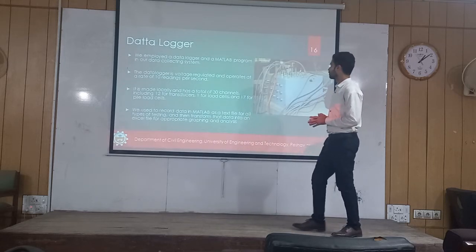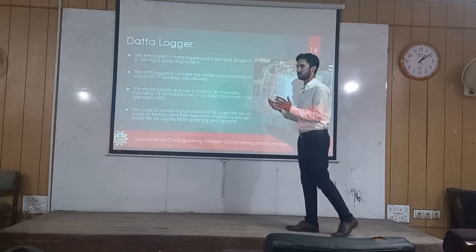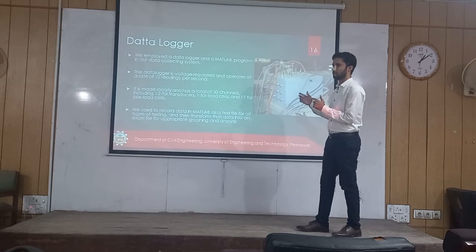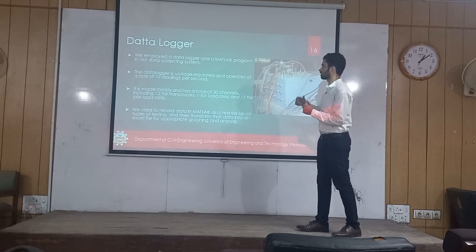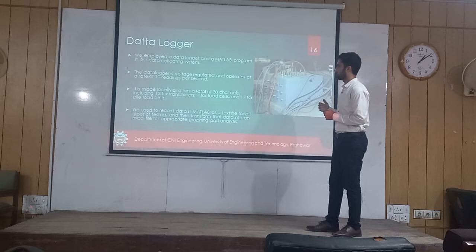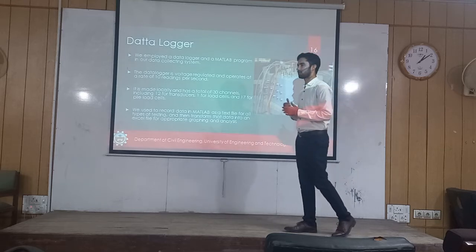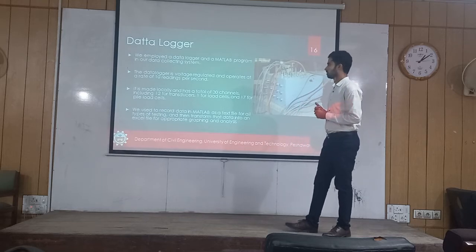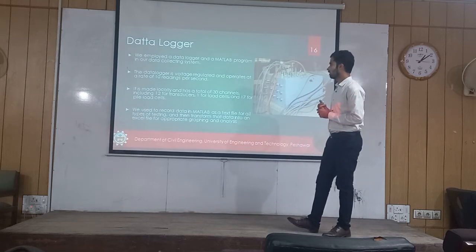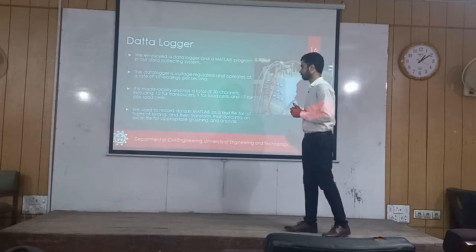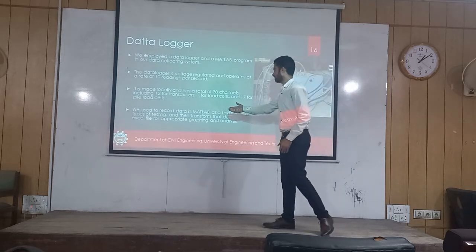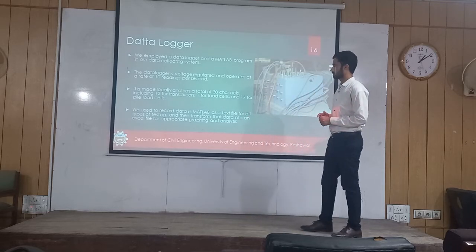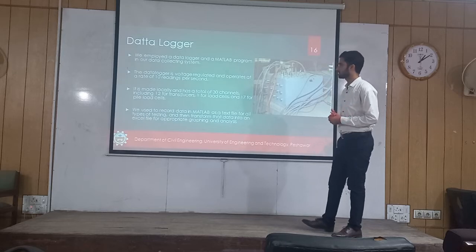Data logger: we use a data logger so that we can collect data from the displacement of piles with the help of MATLAB. The data logger transfers the data from the soil works to MATLAB, and we collect the data on how much displacement is produced when load is applied. There are a total of 30 channels. Among the 30 channels, there are 12 transducers, 1 load cell, and 17 pile load cells. And we record this data in MATLAB as a text file, and the transferred data makes a file for graphics and analysis.